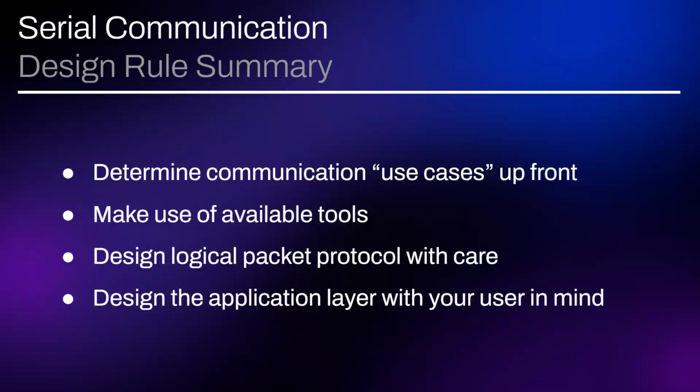It seems like a lot of industrial devices use the older standards. Is that because they're worried about noise in the industrial environment? Yeah, often they'll use what's called RS-422, which is a current loop serial with a longer range than the voltage driven one, but it's still a serial protocol. Is that what you guys use? We use 422 in some cases and 485 in others. What's a 485? It's just a slightly more modern version, I think another current loop.